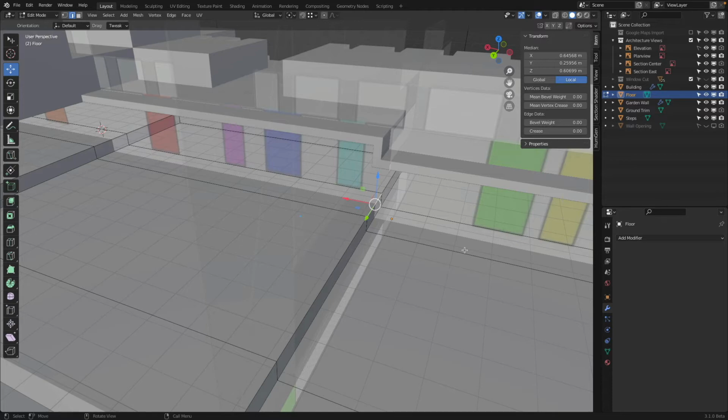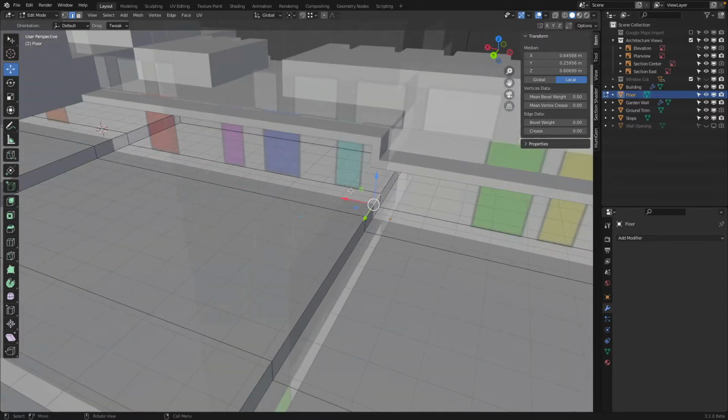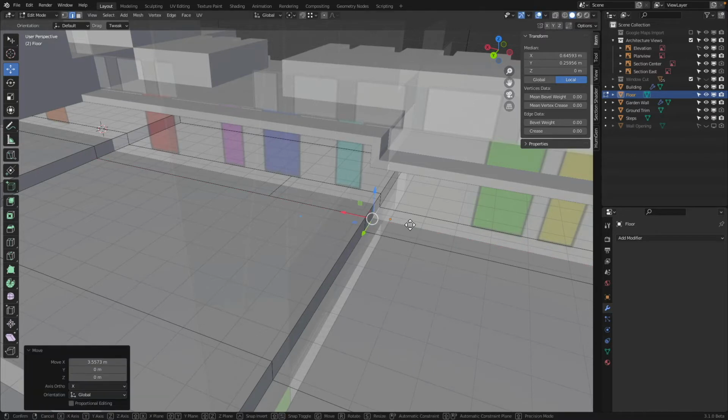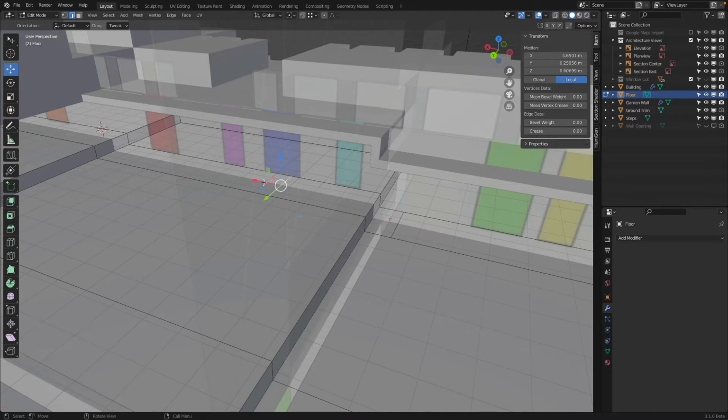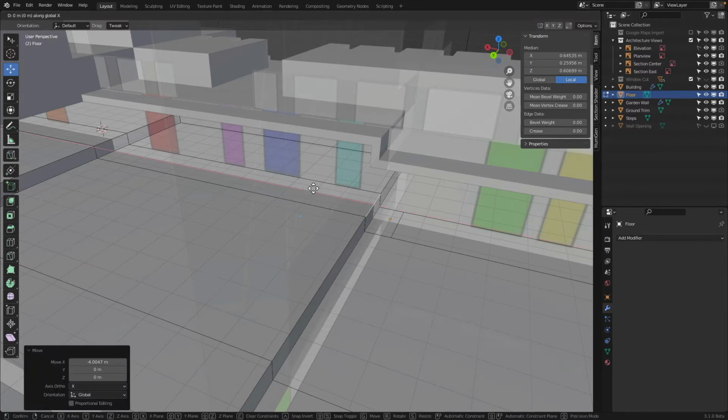So how do we, what's maybe an easy way to do this? So K, click, and this is the Y-axis, so I press Y and click and enter. K, click Y, click and enter. Now, I want to work a little bit clean. So this, I move over and snap, and then I press G and X -1. So move along the X-axis, but -1 meter. This, I move over, snap. This is positive X, GX 1.